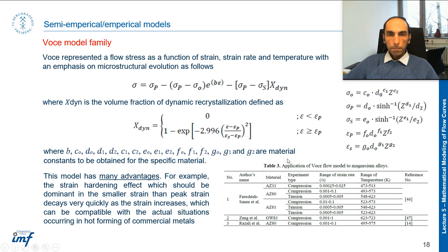And then for the fraction of dynamic recrystallization by itself, Voce suggested this equation, which controls the kinetics of the dynamic recrystallization when the epsilon is higher than epsilon peak.